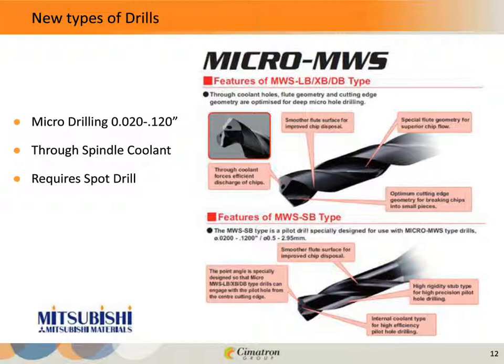And the other thing that I've found out in my research, and again, I'm going to speak in generalities, I know that there was not always a black and white when it comes to some of these applications, but generally speaking, if you're going to be drilling with a drill that's under 100 thousandths, probably you should be considering using a spot drill. And then I think over 1/8 of an inch, depending on what length the drill is, probably maybe you don't need a spot drill. But again, I highly recommend you consult your tooling vendor. But I'm going to show you some differences here on the next page.